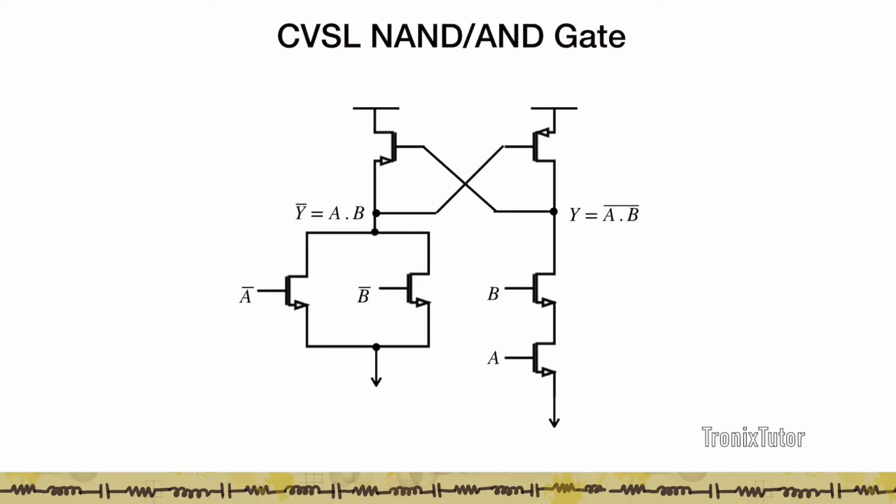So a simple example of creating a NAND gate would be something like this. So here you have the NAND stack. This is your standard NMOS pull down of the NAND stack. So the output here is A and B under the bar. To create the complementary network, we now create this, which consists of A bar and B bar connected in parallel. So for any input combination, one of these networks is going to be pulled down, leading to one of these outputs being pulled to 1 and the other output sent to 0.